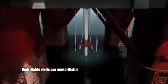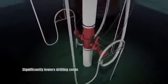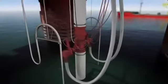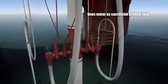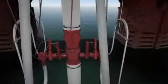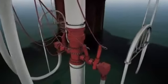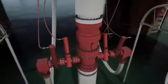By reducing non-productive time associated with fluid loss and major gas influx, pressurized mudcap drilling significantly lowers drilling costs. Costs are also reduced by using water as a sacrificial drilling fluid, instead of pumping expensive fluid systems and lost circulation materials into the formation. In addition, disposal expenses are eliminated because cuttings are injected into the formation along with the drilling fluid.